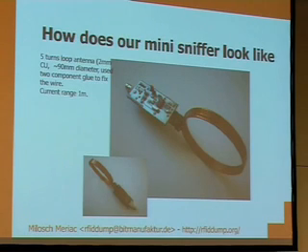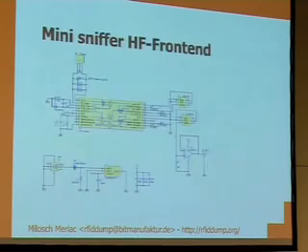Basically, you see the chip that does the downmixing. You have the crystal that creates the 3.68 downmixing frequency, and in the lower picture you see a 9-volt battery and a linear regulator which creates the 5-volt power supply, and you have a high-speed op-amp that buffers the signal so you can do everything you want with the resulting signal.